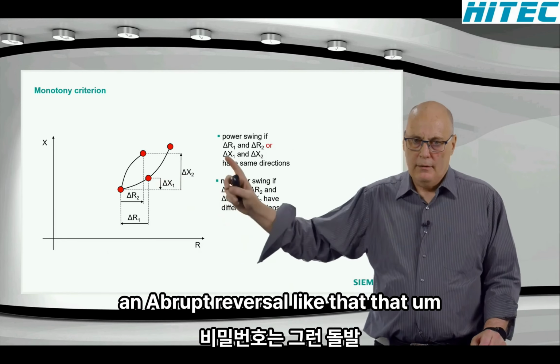Now some diagrams just for interest. This is a power swing, and you can see the power swing blocking at the bottom is picked up. Unfortunately, I must apologize, this is done with SIPROTEC 4, but as I said, the technique is still the same. It's around a 2 Hertz swing oscillation we see here, and you can see the typical characteristic of a swing. As the current increases, the voltage decreases. And you can see around the left there, the power swing is there, and the power swing detection is picking up and blocking.